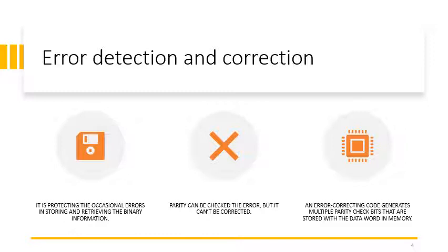We discussed the basic unit that holds a single bit, that is a basic cell, and the interfaces of the basic cell and how we perform read and write operations within it. Then we designed a static RAM of 4x4 words, and we saw what resources are required to implement a static RAM of some specific configuration or capacity.